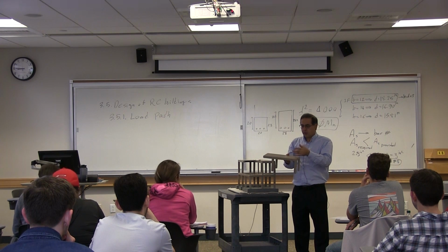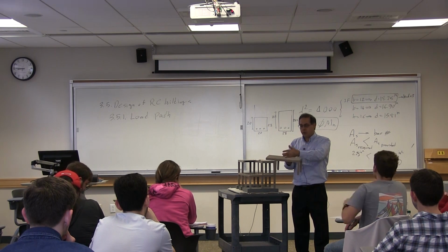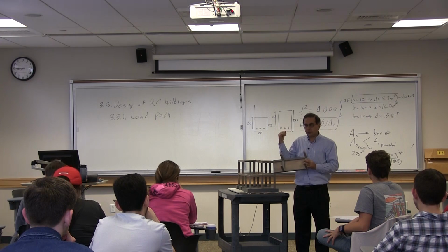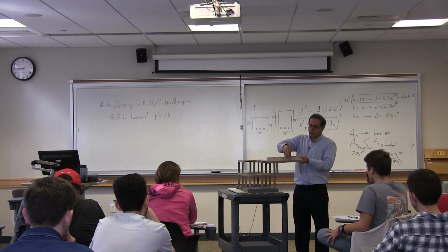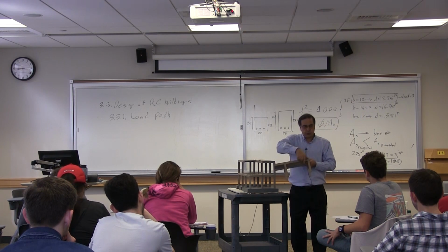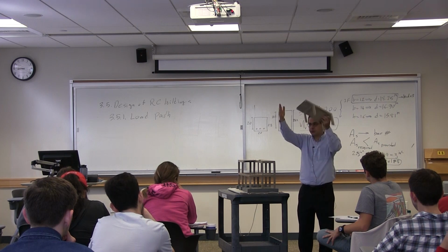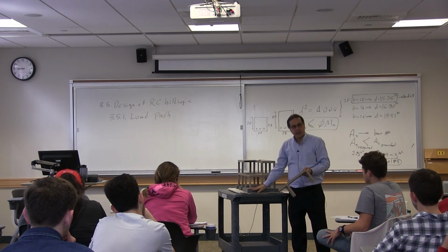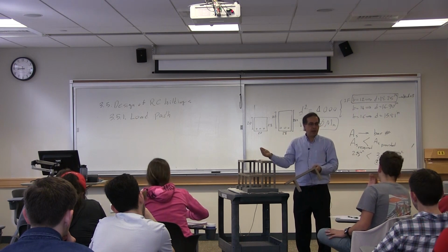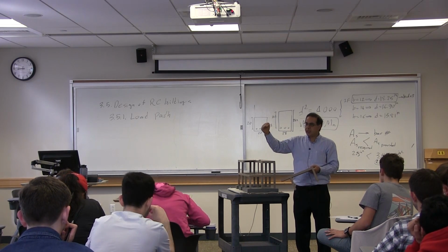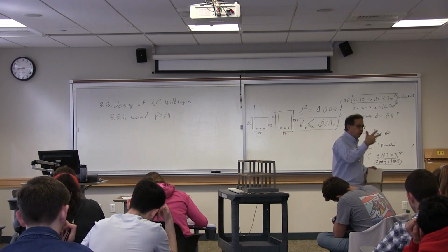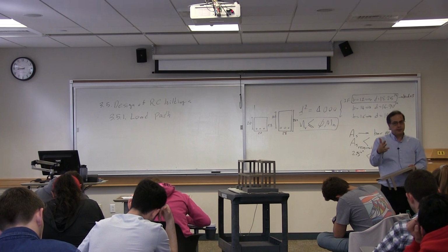One question would be, which beams will take more load? These two beams or these two beams? That we will discuss today. But the load from the floor goes to the beams. The beams would transfer the load to the columns. The columns would bring down the loads to the footings, and the footing would transfer the load to the ground. That is a complete load path from the point of application to the support, which is the ground. Slab to beam, beam to column, column to footing. Okay.